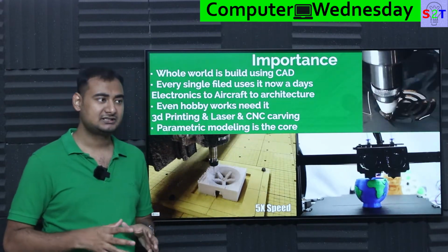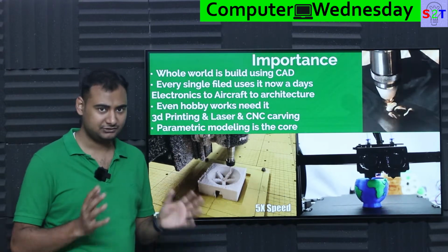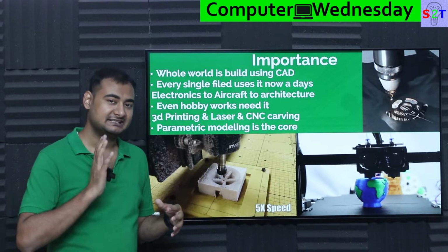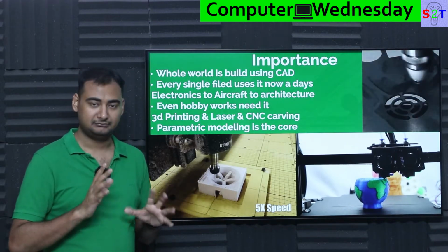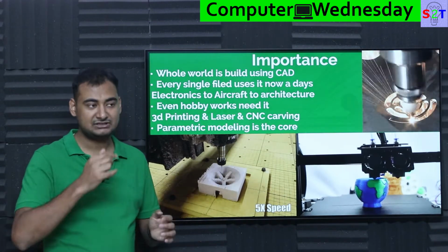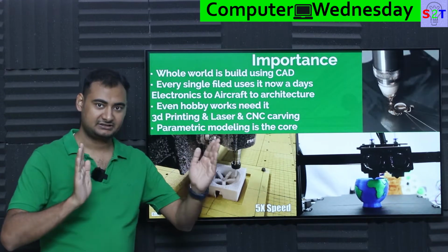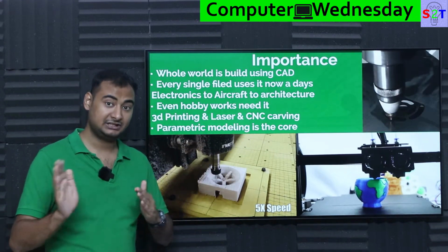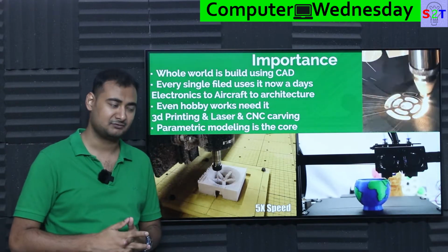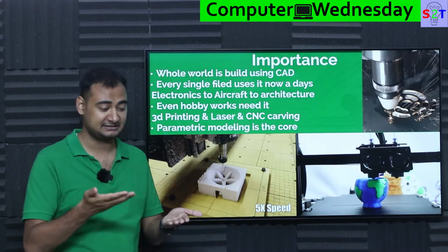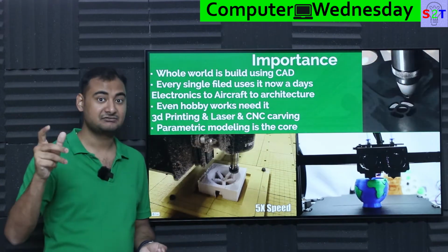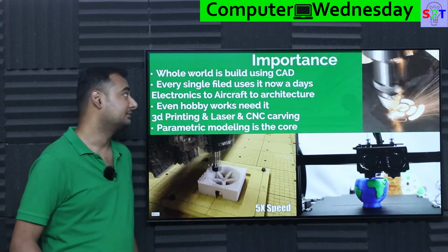Now, parametric modeling is basically defining the whole thing, whatever you are building, be it, let's say, a wheel, a heat sink, whatever have you, is designed by mathematics. And mathematics does not mean you have to do calculation. You simply say, okay, heat sink, that means fins. You define fins as, like, 15 fins, 20 fins. So if you have to change, let's say you're like, hey, dude, I don't think thermal performance is good enough. Or maybe engineering says, dude, it's too expensive to manufacture. You're like, what if I reduce the fin count? You just change one vector, and it changes your whole structure. So that's the whole point.